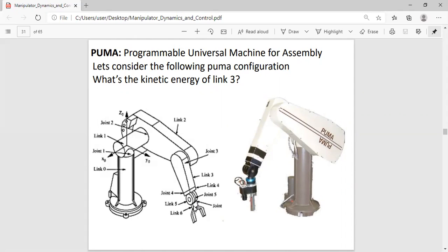To be able to simulate the dynamics here, we will first begin by capturing the potential energy in the system and also capturing the kinetic energy of the system. And then we will use Lagrange, and then we find the angular acceleration on all these joints. From the angular accelerations, we can obtain angular velocities. And then by numerical integration, we can find the angular positions on each of these joints. That way we can have a realistic physics-based dynamic model of the system.